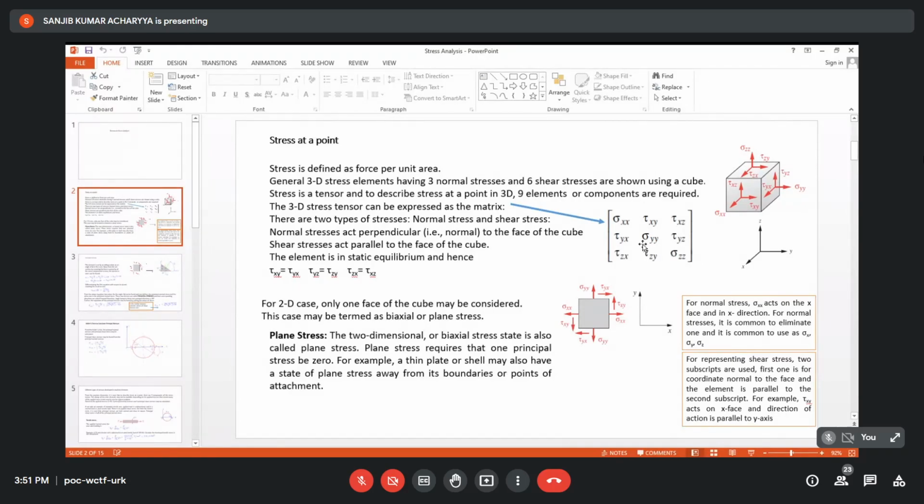Is it true that in every situation only equivalent normal stress can give you the answer? My answer is no. Because there are materials which do not fail because of the normal stress exceeding the permissible stress. Rather, shear stress exceeds the permissible limits. So what is the designer's role? He has to evaluate the maximum shear stress due to combined stress. And we have that formula.